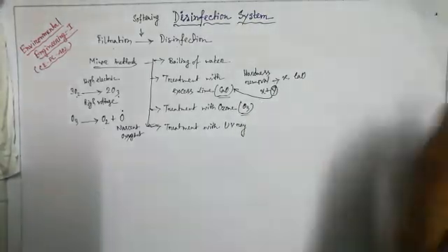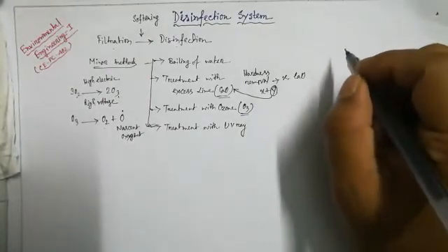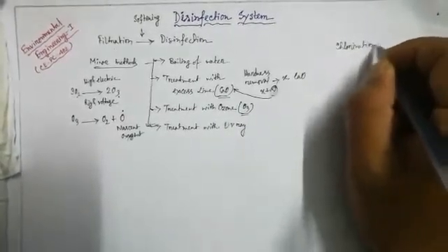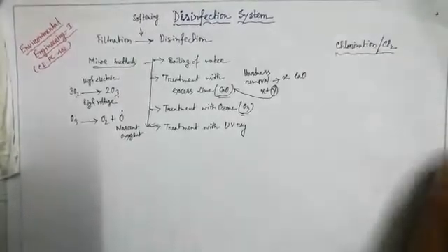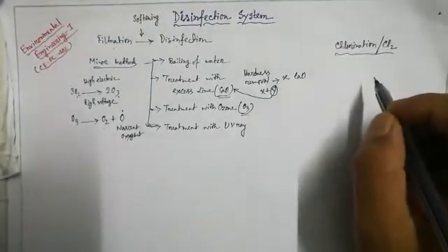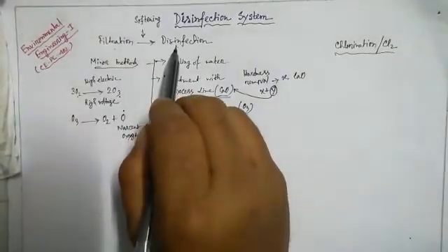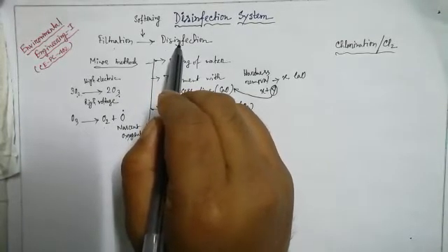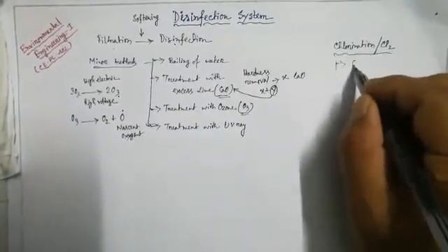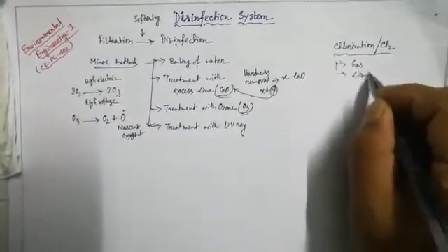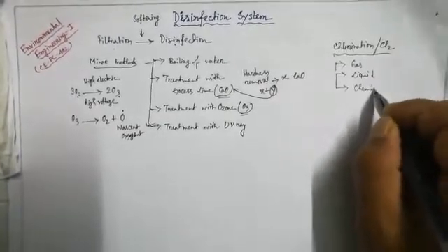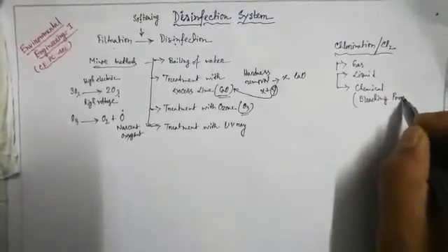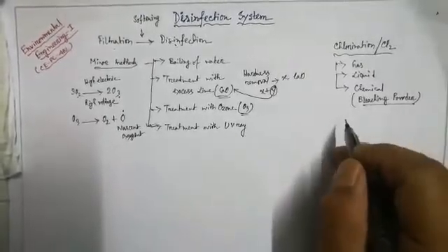Now come to the most effective part, that is the chlorination system, the disinfection process with chlorination. Cl2, addition of chlorine, is known as chlorination. Whenever you have a water sample in the disinfection chamber, coming after the filtration process or from the softening process, you have stored some chlorine. This chlorine can be added in gaseous form, in liquid form, or in chemical form. In chemical form it means bleaching powder. If you add some bleaching powder to water, then Cl2 can be generated from this bleaching powder.